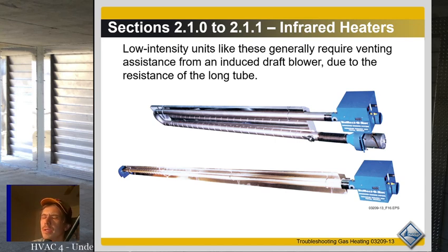Combustion analyzers are extremely important if you're working on oil. I find that on most other equipment, as long as you got gas pressure set right and all that stuff, it's very rare that you really need to do a combustion analysis, but that's just my 2 cents. I mean, if you are doing combustion analysis, that's always much better than not. Combustion analyzers can also help you determine problems like possible cracked heat exchangers and things like that, but it's just not something I've done a ton in my career. It hasn't been up on the scale of things I thought were extremely important. So again, just my 2 cents, not necessarily something to live by.